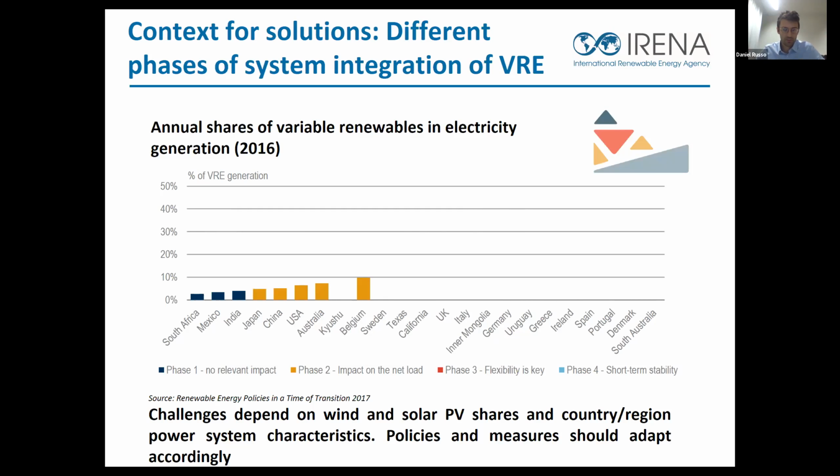So what other sources of generation in the system have to do to accommodate wind and solar generation, which can't necessarily be controlled? You might have to change those practices. This could just mean existing flexibility resources are used more often. Certain plants are changing their operating system. But then as you move past, say, 10% penetration of generation, then new sources of flexibility begin to become important. And that's where we can talk about things like storage or new flexible generators.